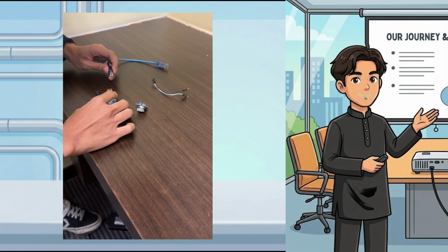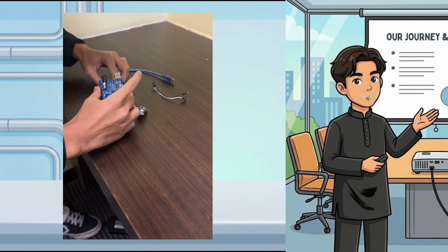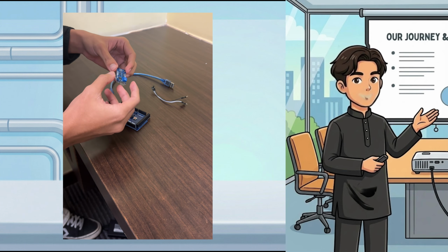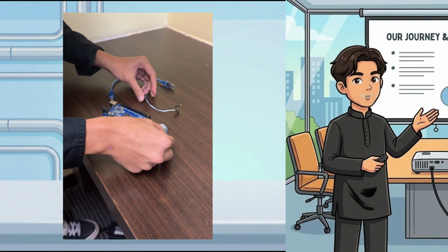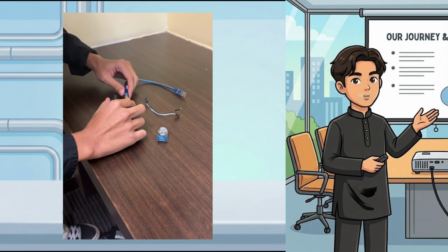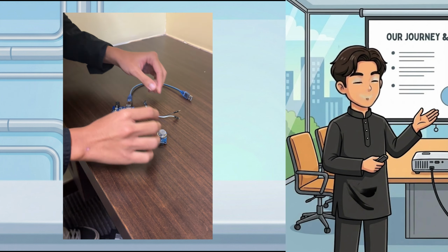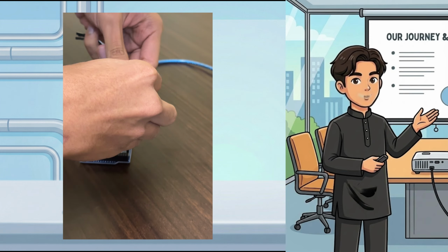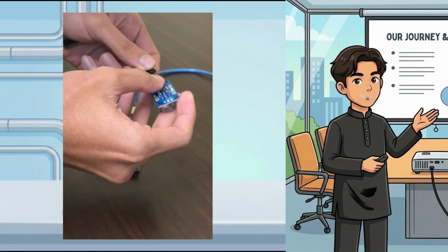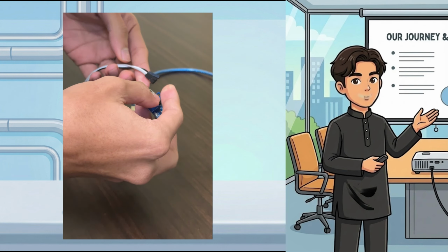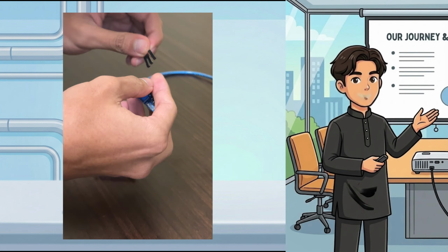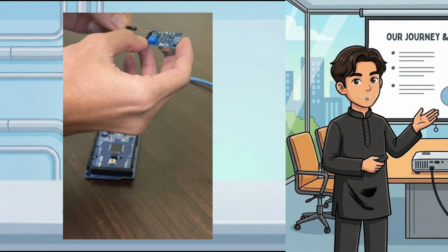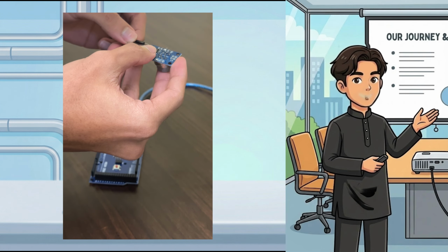Today I want to show you how to connect the hardware. We have the Mega 2560 Arduino, the MQ4 gas detector, a straight cable, and a USB type A cable. First, we connect the USB, and for the gas detector, we take a straight cable and find the three main pins for the connection: A0, GND and VCC, which means voltage.